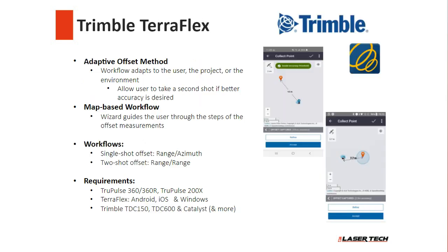We've been a Trimble business partner for many years. We've had a laser interface built in different apps and different software, from Windows to Windows Mobile. The TerraFlex app does have a laser interface built in. This workflow is more adaptive to you. What it does is it takes the accuracy of the laser, the accuracy of the GNSS receiver, and it applies it to that position accuracy that Steve talked about.